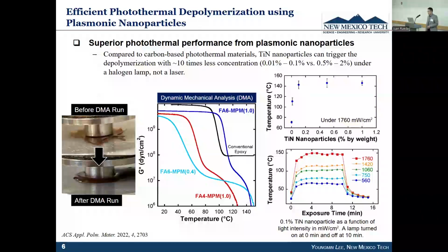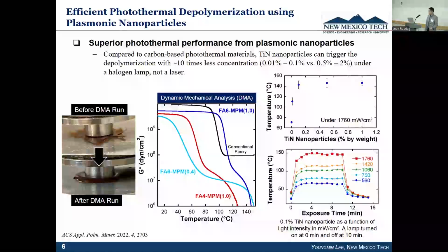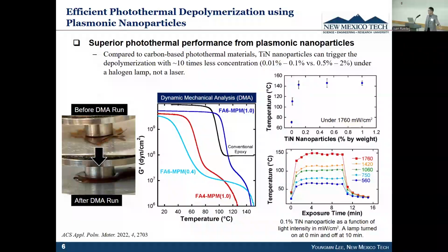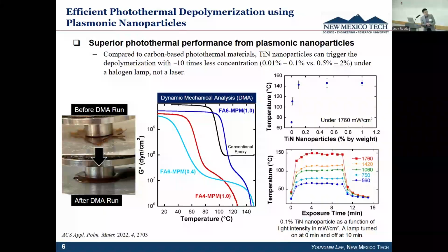The first work we did was to prove our concept, that our material actually goes through a transition from network state to segment state. This is rheology data: the y-axis is viscoelastic modulus, the x-axis is temperature. At low temperature, they have high modulus; it's a strong material. As it heats up, they pass through the glass transition, the molecular chains gain mobility, and they soften.